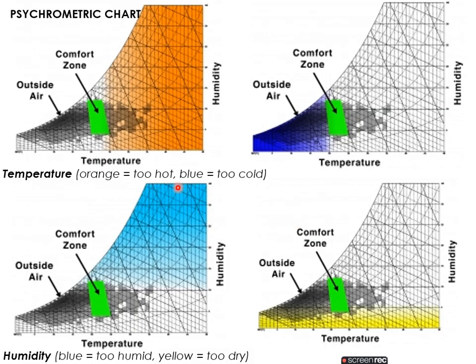Now if a lot of data points fall on the right side of the chart, in the orange region, it means the region is too hot. For example, Jaisalmer and Jodhpur are hotter regions in India. If your points fall on the left side of the chart, it means it is too cold, like Shimla or Shillong. If the points fall on the topmost right corner of the chart, it means it is humid, like Chennai and a few regions like Chennai.